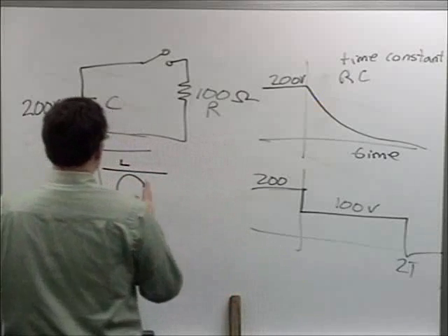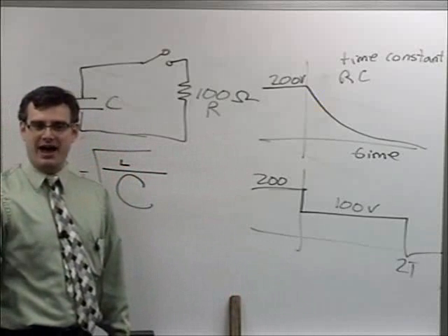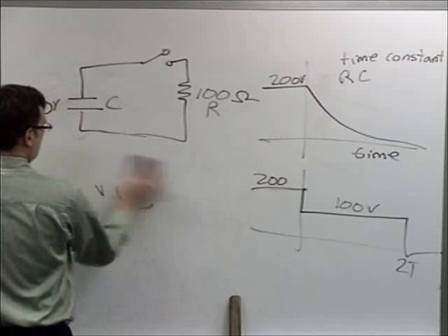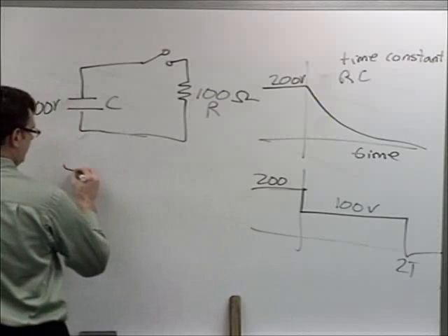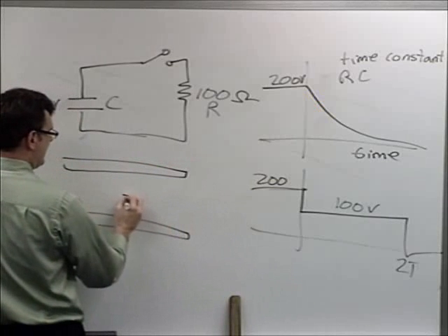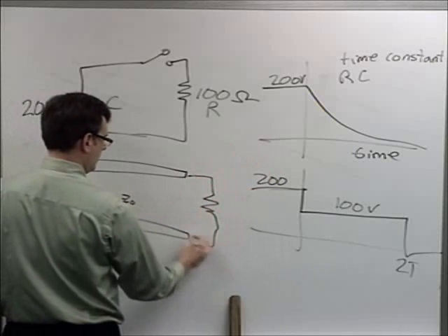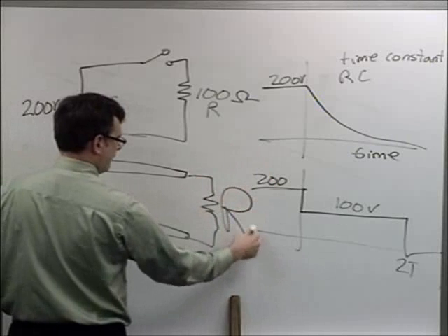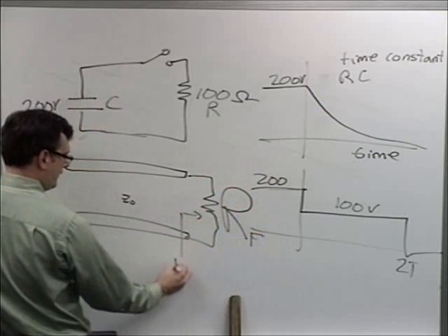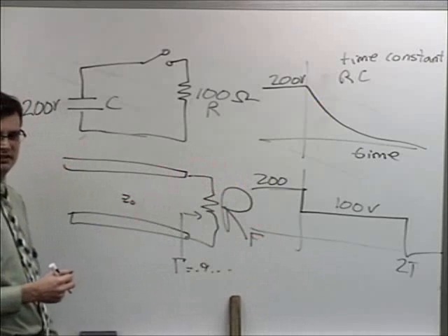So usually, between your finger and the capacitor, there's going to be a big mismatch, right? You're going to get a really strong reflection coefficient from your tiny little Z0, and by comparison, your extremely large R finger, R sub F. And the reflection coefficient is going to be like positive 0.9 something something.